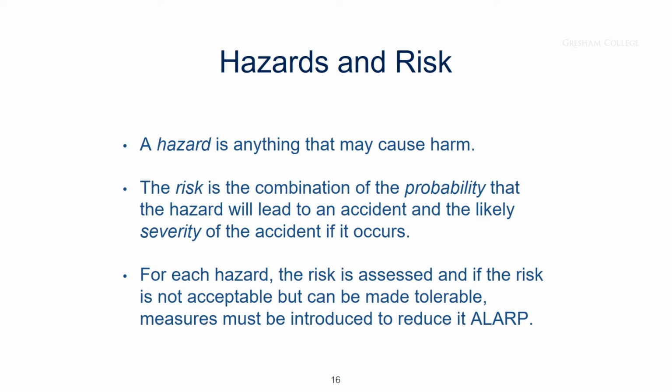We talk about hazards, anything that causes harm. So hazard analysis is looking for the hazards. What could possibly go wrong? And many industries have got fairly well-developed and experience-based ways of looking for these things. The chemical industry will run a set of keywords against a particular situation, you know, too hot, too cold, too quick, too slow, too high pressure, too low pressure, in order to test whether there are conditions here that could occur and could then lead to a need to do further analysis.